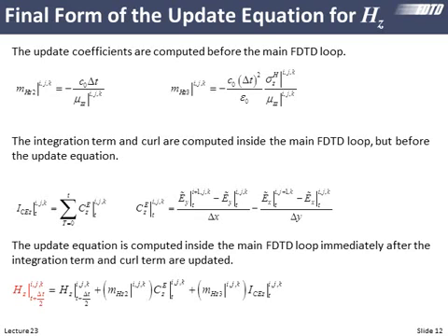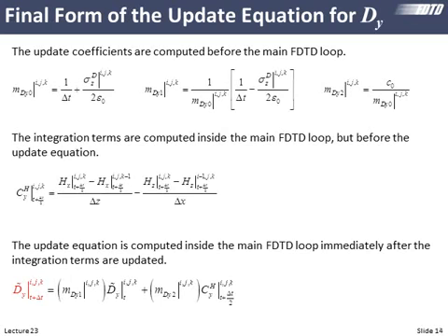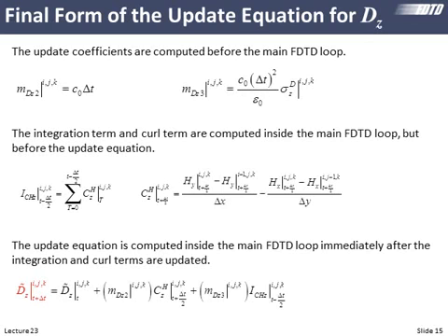And remember, we will separate this for an integration term at the top and another integration term at the bottom. It is certainly not incorrect to just do this integration term everywhere. It's just very inefficient now that we have gone to 3 dimensions. So we probably don't want to do that. Our dx, no integration terms. Our dy, there's still no integration terms. And then finally dz, again, here's a field polarized going into the PML.